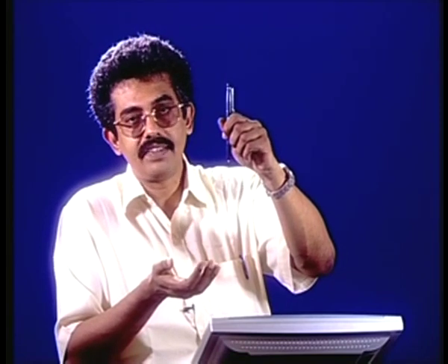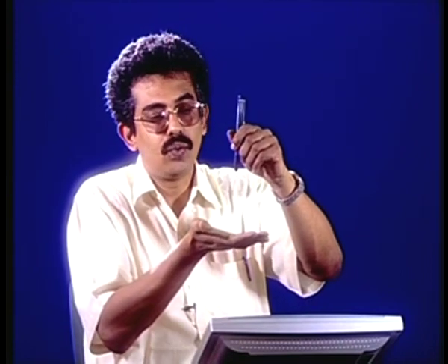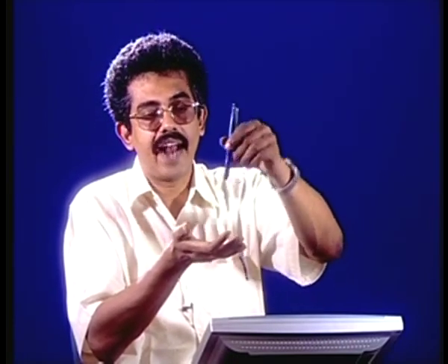For example, if you take another process called drilling. In drilling also it is the workpiece which has 2-dimensional motion, because you may like to drill a hole anywhere on the workpiece. On the other hand, the tool is rotating generally at very high speed. At the same time, it can come down to actually drill a hole.